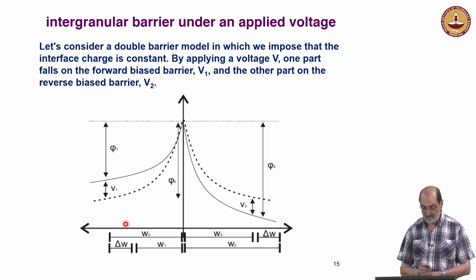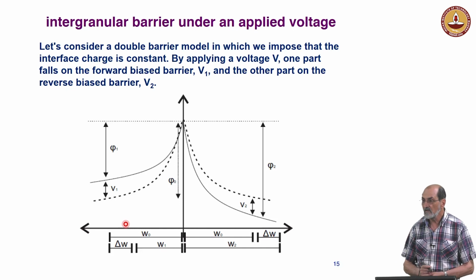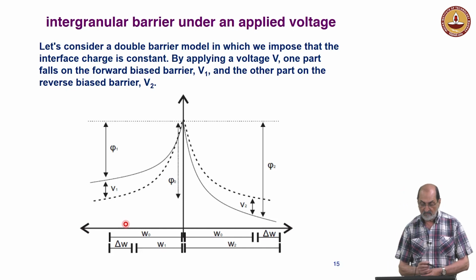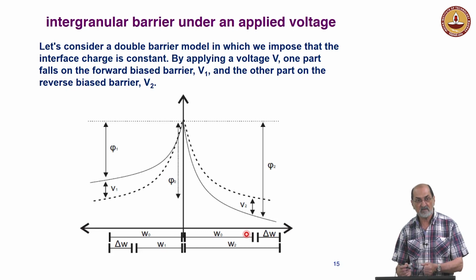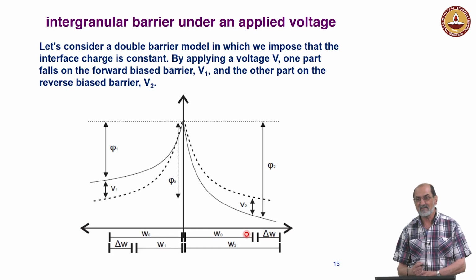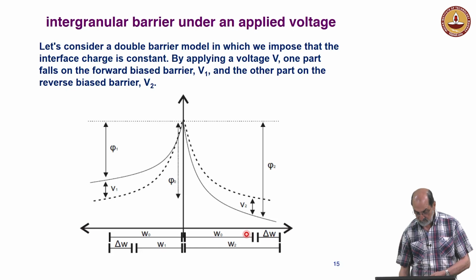And there is a technique usually done to calculate the barrier heights and so on. But if the voltage does not drop completely on the diode which is inversely biased, the results can be whatever they want. This is a typical, very used technique, but I think it doesn't work well.